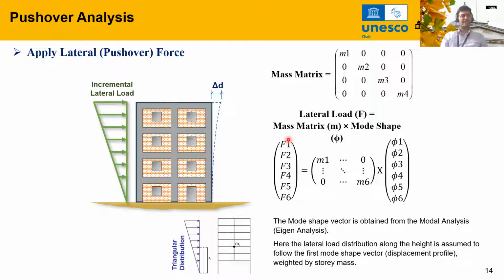So you just get this vector, and then you can start monotonically increasing it to whatever value it takes until the collapse occurs. Okay, you can multiply this by 100 times or 1,000 times, and then you can keep on increasing monotonically until you get the collapse.